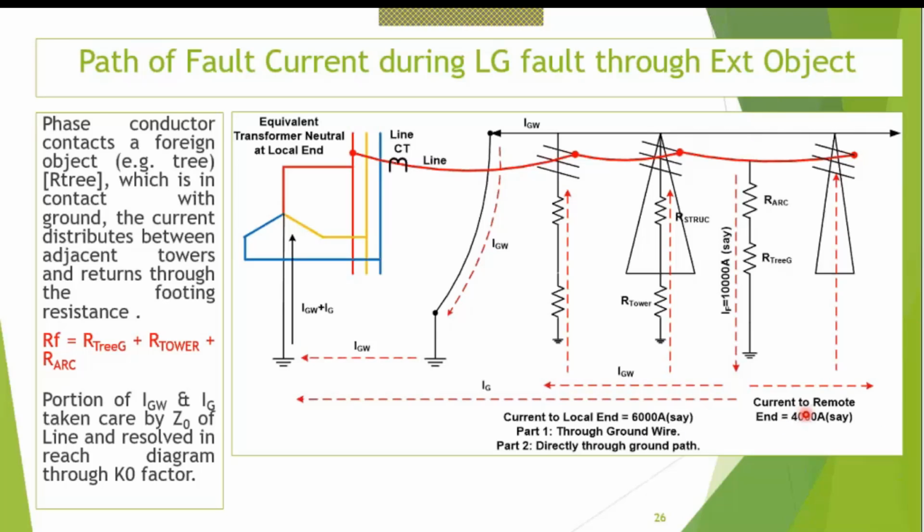Remote end we are forgetting. Let us forget for now. Let us concentrate only on the local end. Whatever is happening on the local end will also happen at the remote end. The remote end relay will take care of it. The local end, what will happen? This current has to return to the base, to the source.